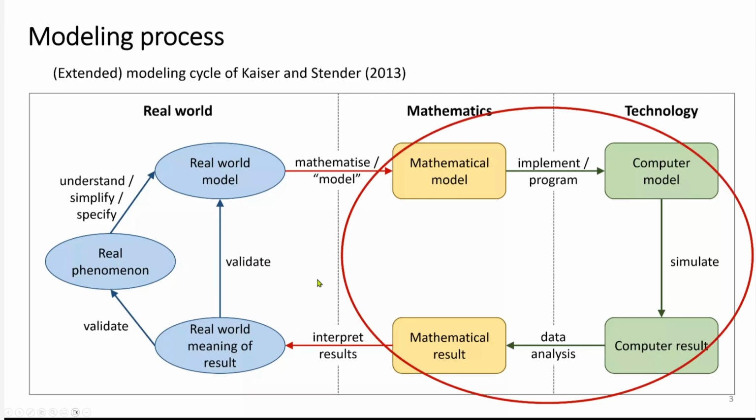this part. So Chrono is not going to help you model, right? So all these things you have to do yourself. Once you decided on a real world model and say, well, it's a simple pendulum, or it's a connection of bodies that represent a vehicle, well, then Chrono can help you put together that mathematical model, and then it has implemented the numerical methods to solve whatever equations you end up with here, whether they're ODEs, DAEs, PDEs, and so on.